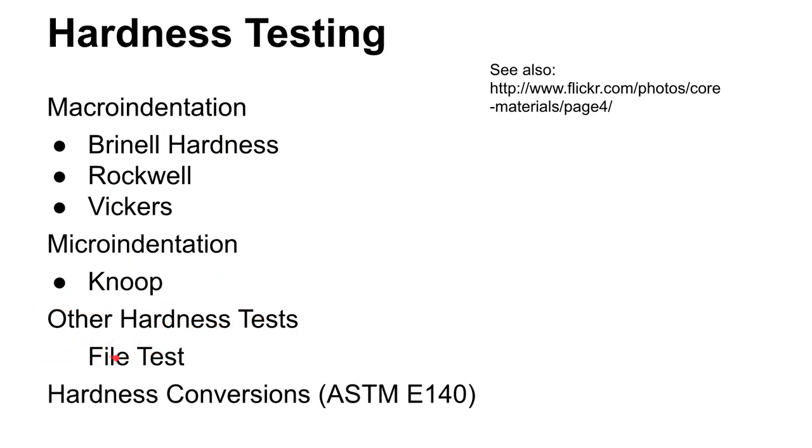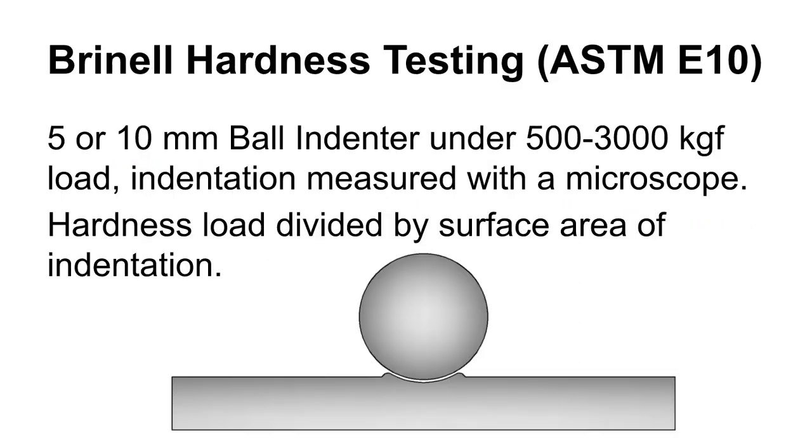A good cheap shop way is a file test, and we'll also use a little handheld hardness tester in the lab, but it will actually be doing a Rockwell test or Brinell test depending on how we set it up. All right, so first of all, Brinell hardness.